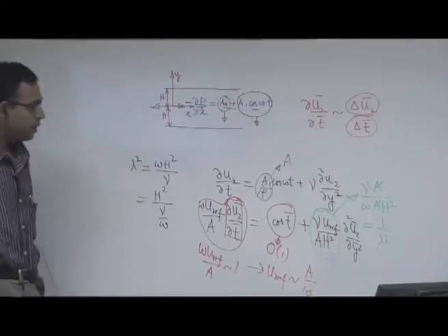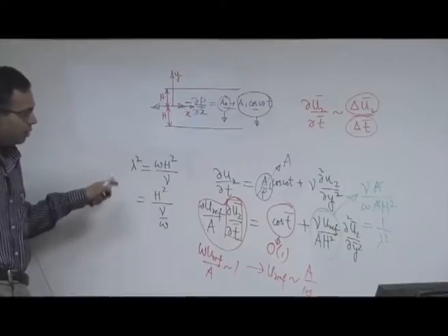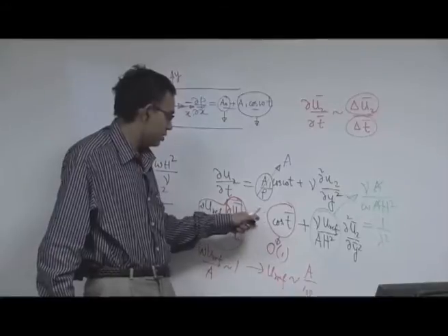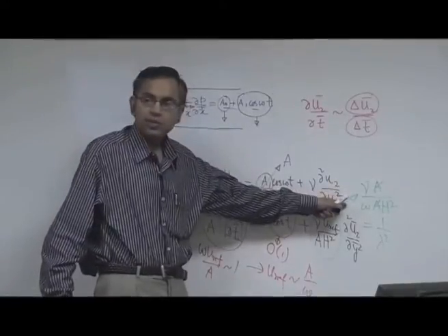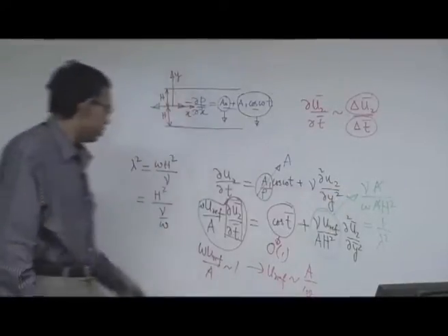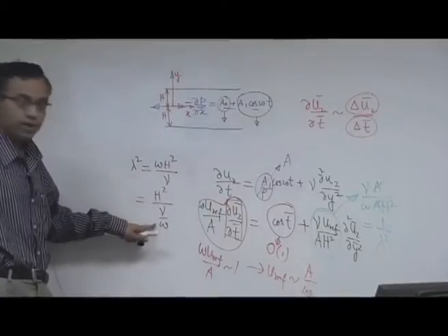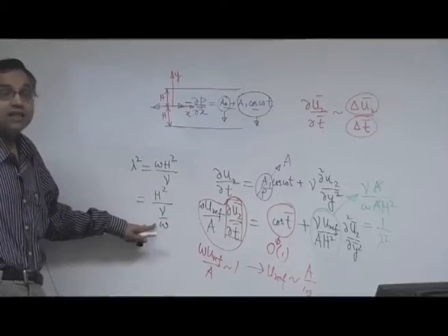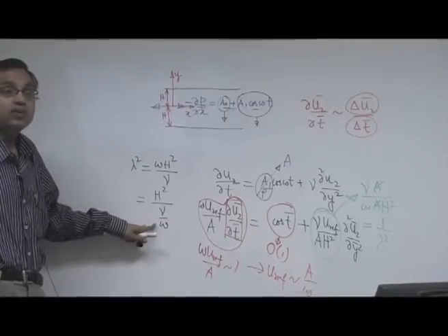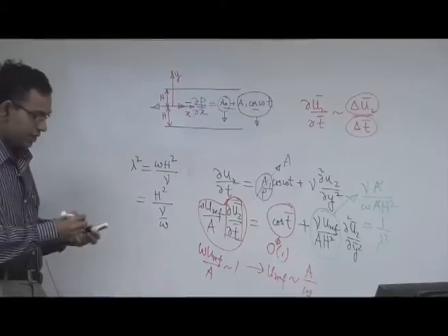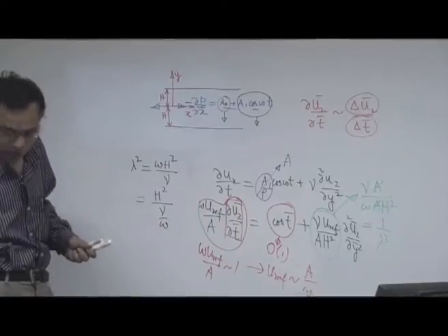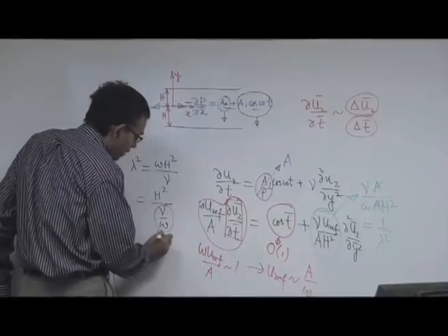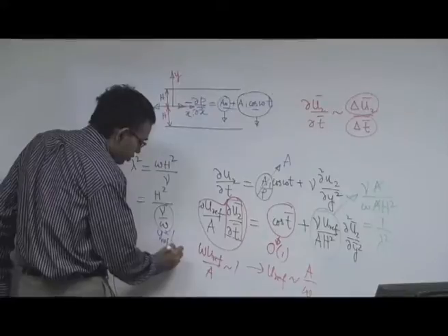Right. See, first of all, because all the coefficients are non-dimensional, this also has to be non-dimensional, right. So, nu by omega has to be square of some length scale. What is that length scale? That is the length scale that we got from the Stokes second problem, right. If you just look into your notes for the Stokes second problem, you will see that this is y reference square for Stokes second problem.